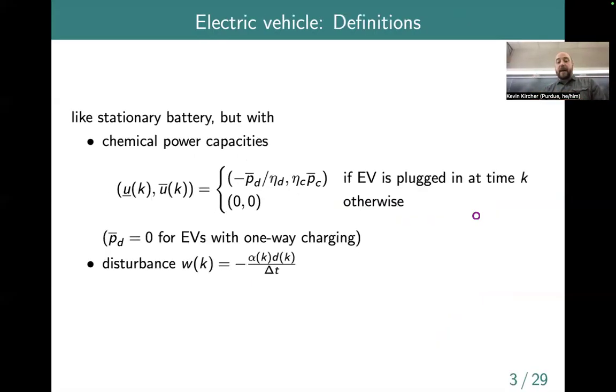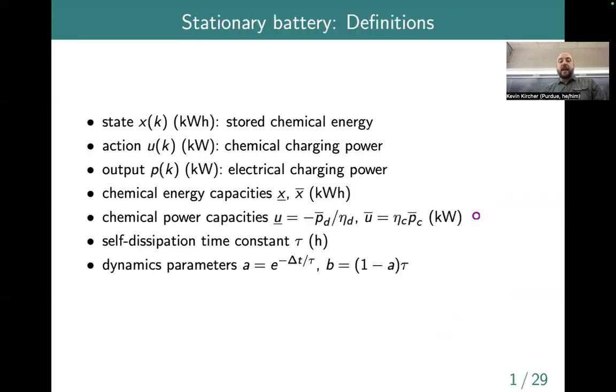Now you could look back at this battery model and say, on a normal day we charge overnight. In California, say, on a normal day there's tons of solar from 10 a.m. to 4 p.m., so our normal pattern is we charge like a bandit during those periods, and then we discharge in the late afternoon, when solar power is ramping down and gas power is ramping up.